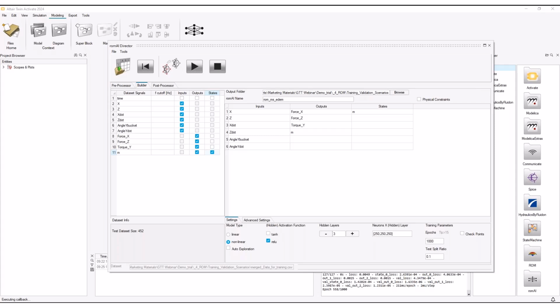Hidden layers is the number of layers that you have in between input and output for your neural network. So in this case, you have 3 hidden layers. And then here you specify how many neurons you have in each of the hidden layers. It is generally good practice to have the neuron numbers in each of the layers be the same, but you don't necessarily have to. Just a note on these layers: in most engineering problems, you only need 2 or 3 layers, and in this case, I'm just using 3 layers, but you can sometimes get away with 2 layers also. I've never seen anybody use 10 layers, but maybe that is a case that can happen.